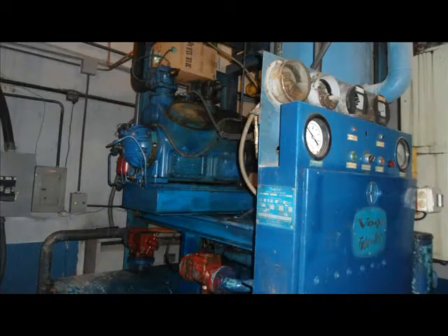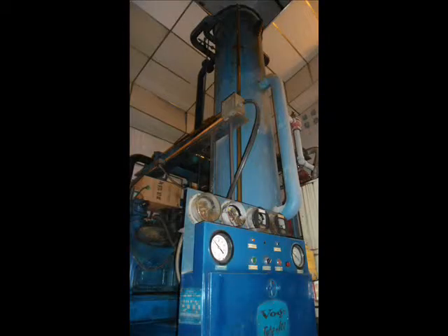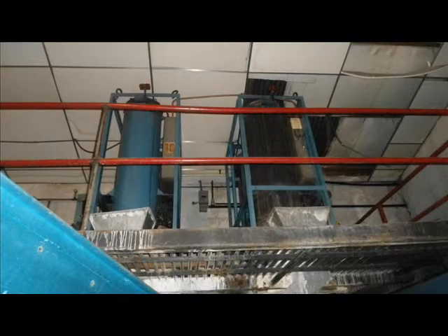This process involves modern equipment of big capacity, working with lab technology to produce ice, with a cyclic frosting system based on the use of ammonia that allows a minimal environmental harm. The process involves a refrigerator mechanism with an evaporator, a mechanism to slightly defrost the ice formed around the protruding parts and to cause it to fall off.